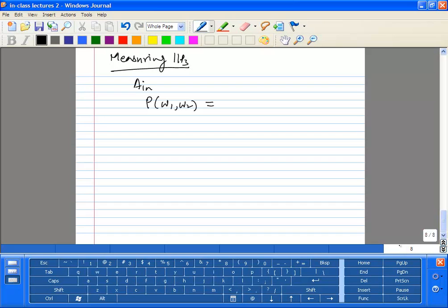Yes, actually that is due to higher order terms. We have assumed a cubic. If you assume a cubic, you'll never get a bend; you'll keep going. But in reality, if you take a real system, you can never represent it just by a cubic. You will usually have a fifth order, seventh order, and so on. Just like your higher orders cause compression in your first order, even higher orders will cause compression in your third order characteristic. So that will cause your IM3 curve also to compress.